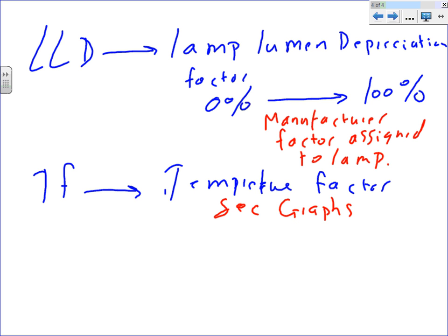Anyway, every fixture, this doesn't mean, guys, that it applies for all fixtures. It's just an example of how the temperature can affect the fixture. Typically, if the temperature is very low, the lumens will go down. If the temperature is very high, the lumens will go down. So there's kind of a range of temperature that can give you the ultimate lumens out of a fixture. The ultimate lumens. Any question, guys? Any question about these factors?